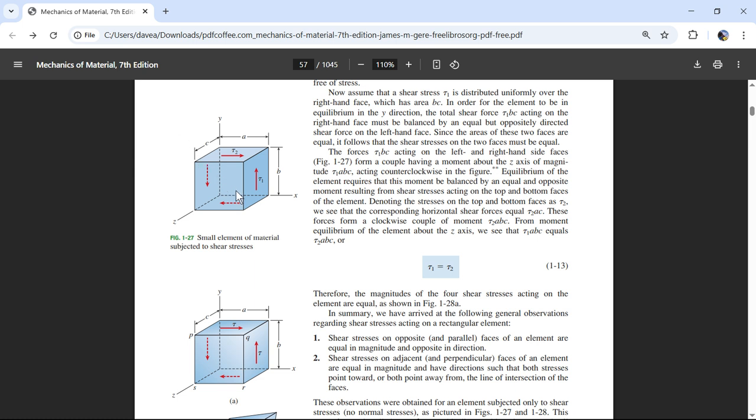And so that means I have a shear stress along that area, and I'm going to have normal compressive or tensile stresses along that area. And even the shear, I don't know what direction it's going, but those shear stresses are associated with forces.